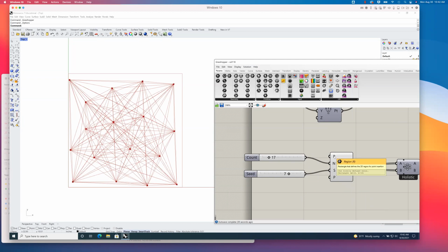So it needs a rectangle to define the region. That's going to place a bunch of points inside of and won't go outside of. So in this case, I gave it a width and a height of 18, starting at the 0 point and going up and out 18 units each.